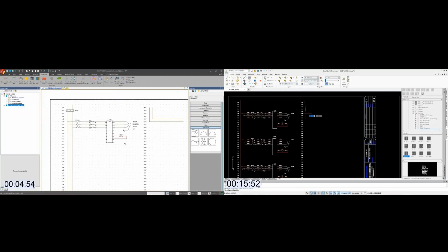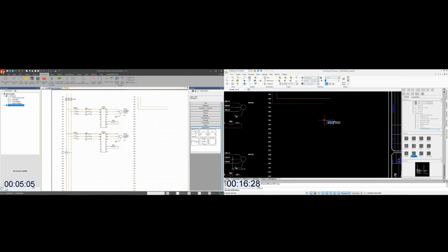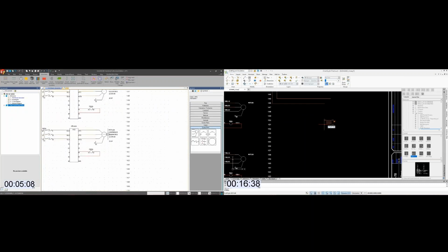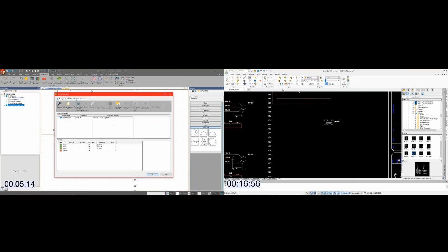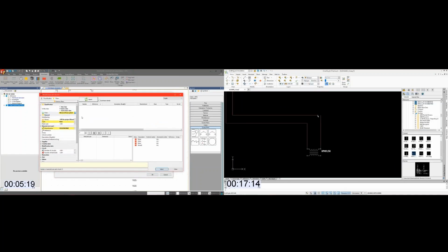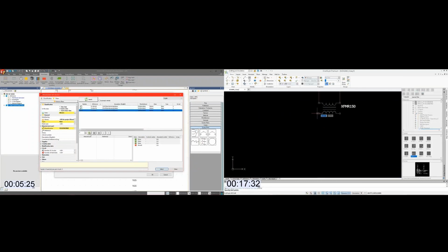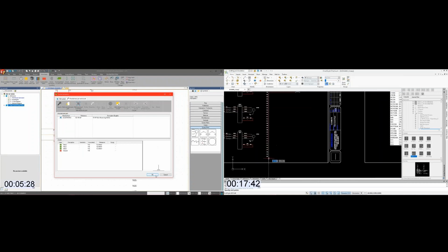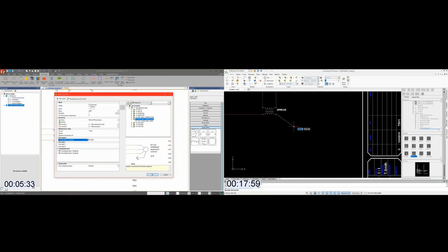But what's really nice is what I'm about to do over here in SOLIDWORKS Electrical. I'm going to do a copy and paste similar to what I did over here in DraftSite to get those 3 circuits. But what's nice about copy and paste in SOLIDWORKS Electrical, it's fully intelligent. I just copied and pasted, and you're going to notice all these tags updated and remained unique. However, this particular motor needs to be sized up, so it had the part number on it before. I simply remove the part number, grab my new motor that I want to work with, and then I've just updated that particular circuit. So I didn't have to go in and change any attributes or anything. So copy and paste keeps it unique. So 5.5 minutes in and got 2 circuits done.